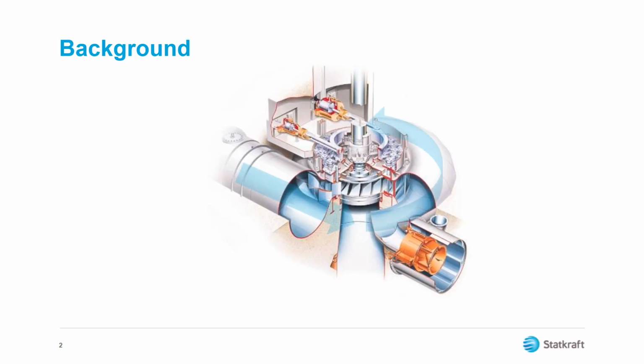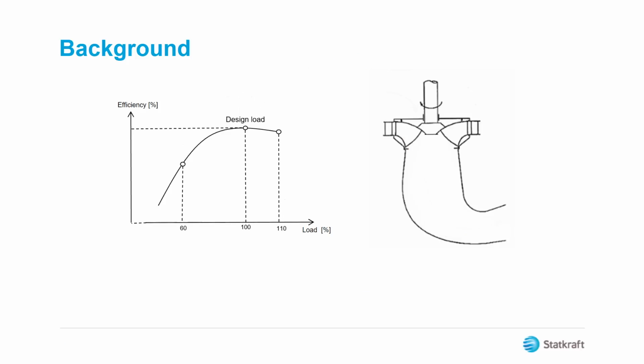As the water is distributed to the runner, the energy contained in the water is transformed by the turbine. After passing through the runner, the water should drop down the draft tube, depleted of all potential and kinetic energy. This is, however, only in theory. At the design load, the efficiency is at its peak. That means that the turbine will extract almost all the energy from the water. This results in a smooth flow through the draft tube.